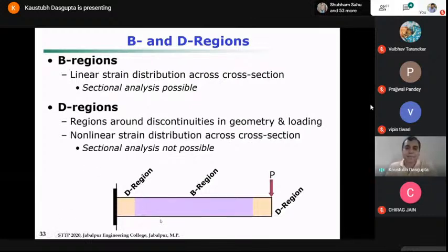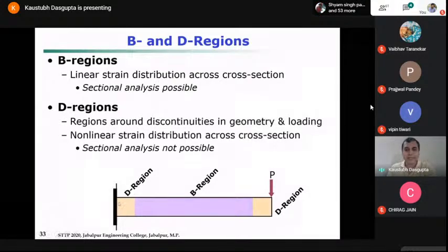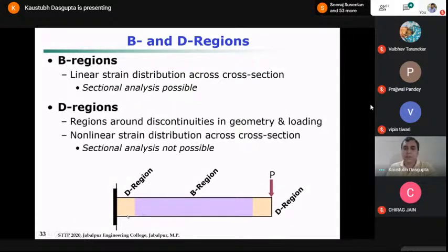The simplest example is if you take a cantilever beam with a vertical concentrated load at the tip, you expect a bending deformation, nicely bent with tensile stresses at the top surface and compressive stresses at the bottom. Now what happens is, whenever you have the material idealized with linear, elastic, homogeneous, isotropic behavior, we tend to use the beam bending equation to evaluate the bending stresses.